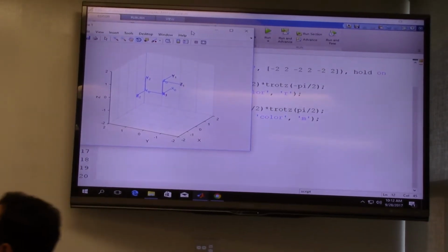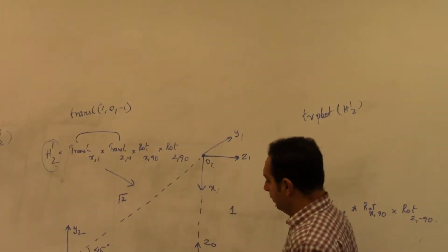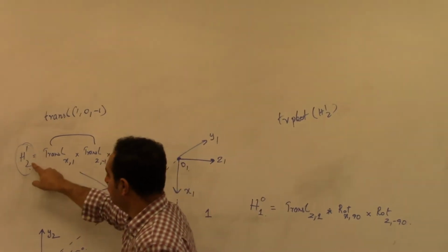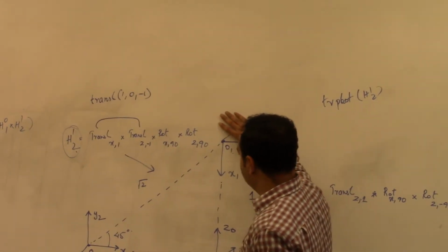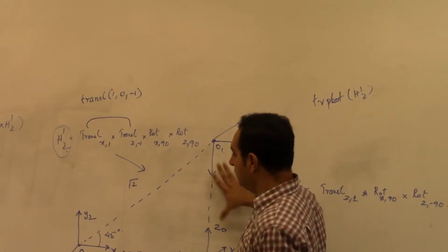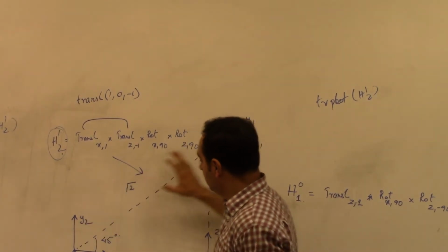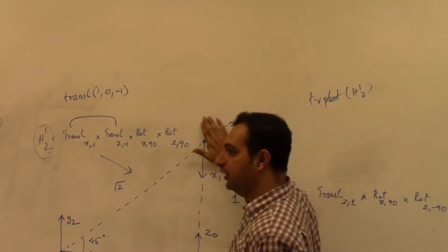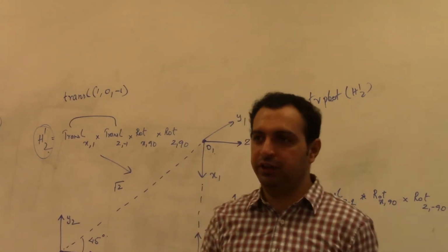So always make sure that when you're going like this, you have to consider that when you plot it, if the transformation is from 1 to 2 like this, you always have to multiply it by the earlier transformation from the origin, because what defines this axis is a transformation from 0 to 1. If you miss out that, then this will not be pieced together, because the basic transformation is missing. Unless it has data about how this was defined, you cannot define a relationship between this and this. You cannot visualize the relationship between the other two axes.